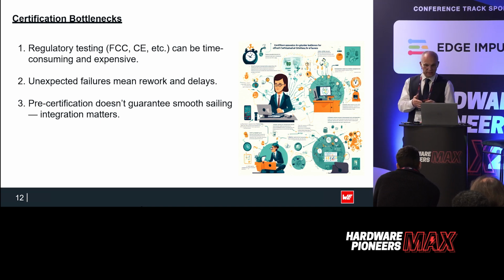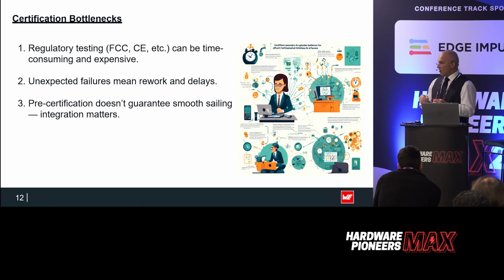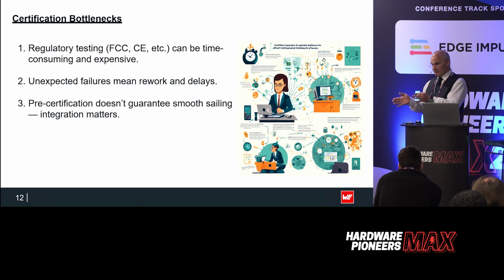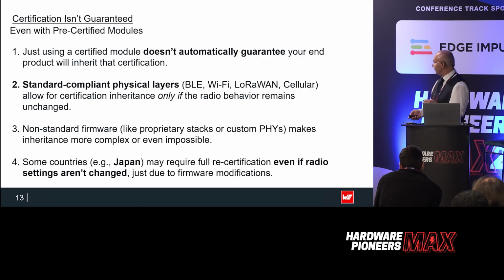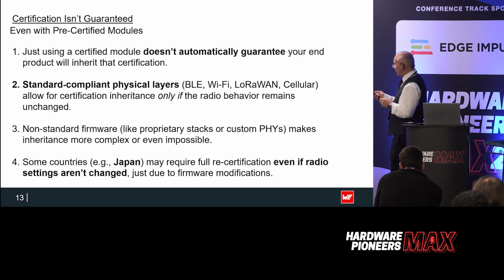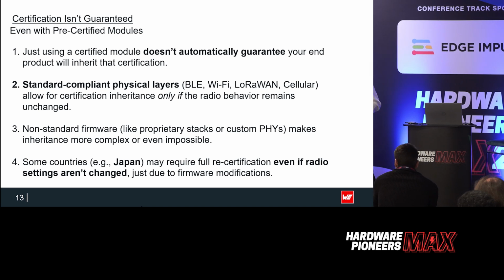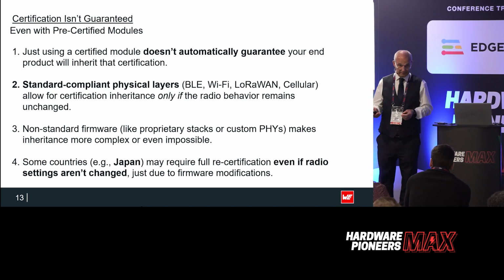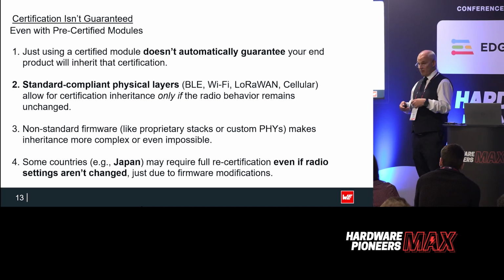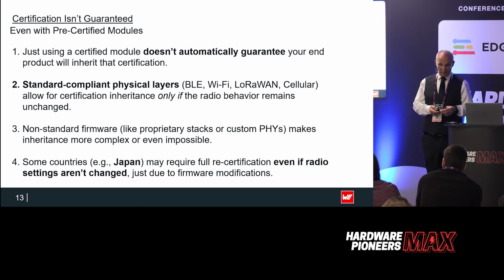The only limitation I would say is not all countries will accept you writing custom firmware, even though you can say it's been tested before. So it can be difficult. Even with a certified module, it doesn't automatically guarantee you're going to pass, because you might be altering the power levels of the RF transmitter, or the duty cycle of it. Okay, you might not conform to Bluetooth standards.